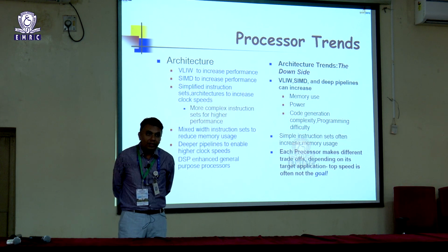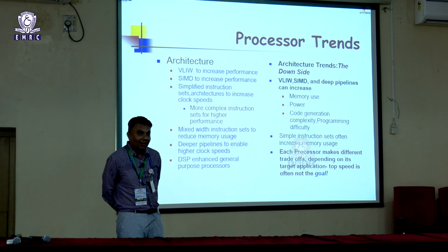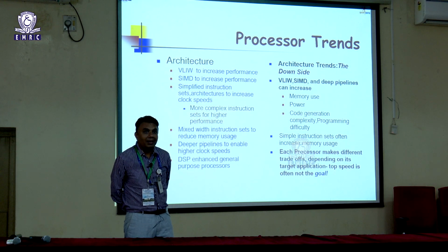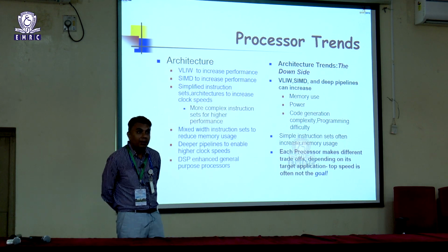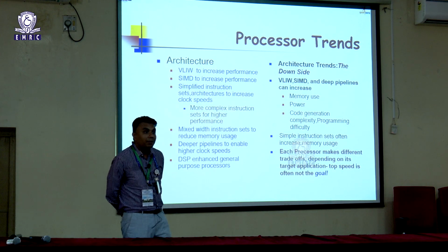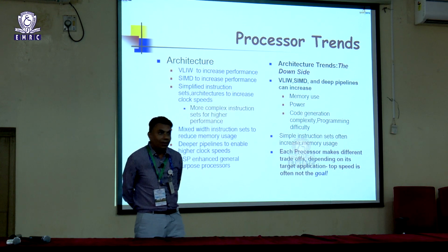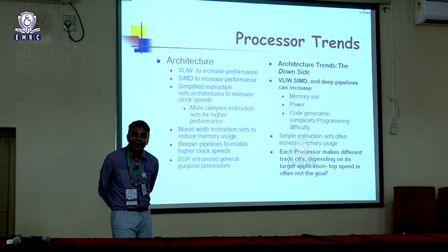But the problem with this type of processor is they are very power hungry. So you have to select carefully. You cannot directly select any advanced DSP processor, because onboard design is power constrained as well. You cannot have infinite power, because all the power we are getting from the satellite is from the solar panel, and solar panel has a limited power generation capacity. So based on our application, we try to use the minimum DSP processor we can, not the maximum.